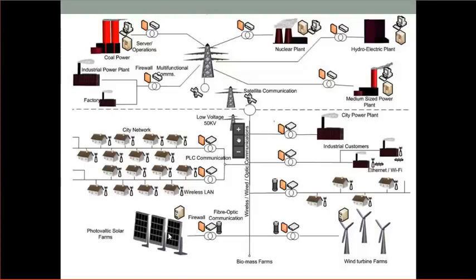Here's another problem that I didn't cover that I probably should have. Let's say the wind power's operating at night. Let's say I'm getting a lot of wind at night. Well, that's when my nuclear plant would be running at 1,000 megawatts. So now maybe I need to bring my power plant down from 1,000 to 950 megawatts because I got 50 megawatts of wind generation.